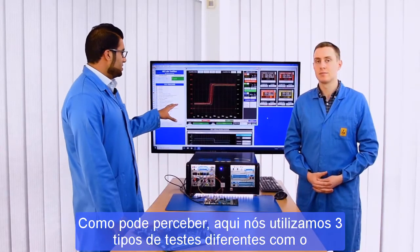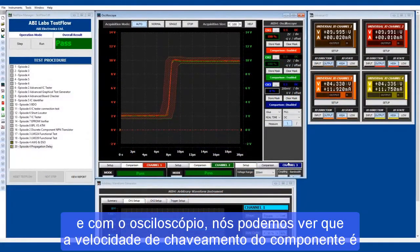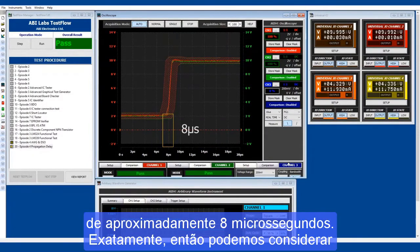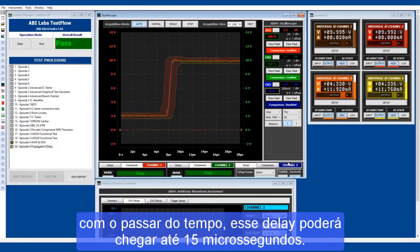So as you can see here, we're using 3 different instruments from the MIS4 at the same time. And with the oscilloscope, we can see that the switching speed of our device is approximately 8 microseconds. Exactly. So this is a fresh PCB with a brand new optocoupler. So it's switching at about 8 microseconds. In the future, this might get delayed from age to about 15 microseconds.